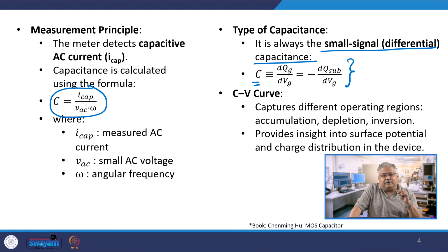So the charge in the oxide layer, the trap layers and the inversion layer must all be equal to the depletion layer charge, that is, the substrate charge. That is the reason any change you make on the gate side with respect to the applied gate voltage should be reflected by the corresponding change in the substrate charge with respect to gate voltage.